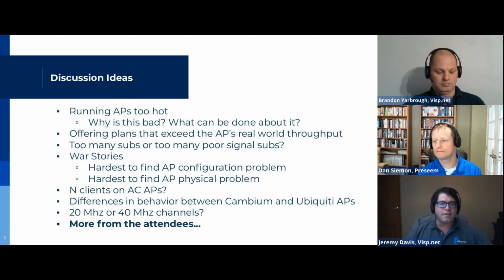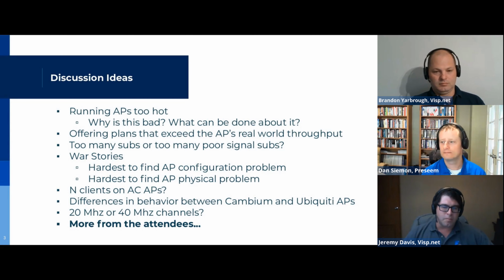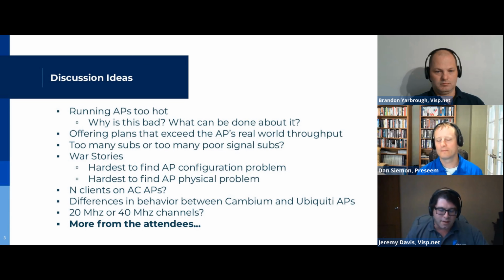I've seen access points where all the customers were within a mile, all had great modulation, and you see tremendous performance. But even as few as 1 or 2 customers that have bad signals will degrade the entire scheduler. When you're thinking about a schedule as pieces of pie, the pie is symmetrical, and it can only be as efficient as the worst piece of the pie, essentially.